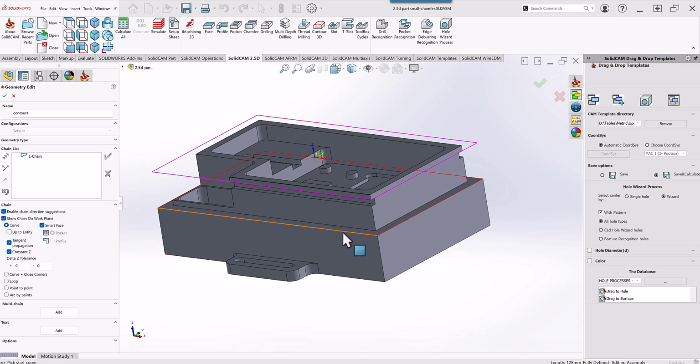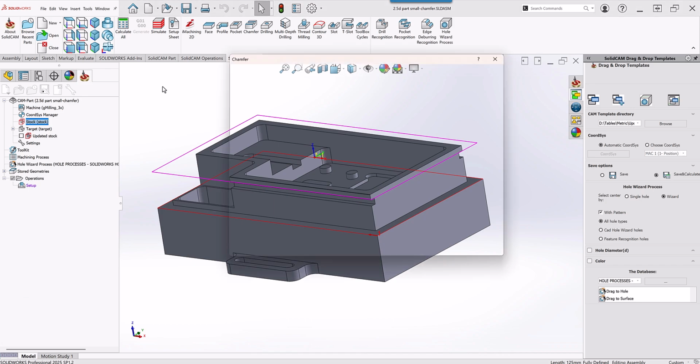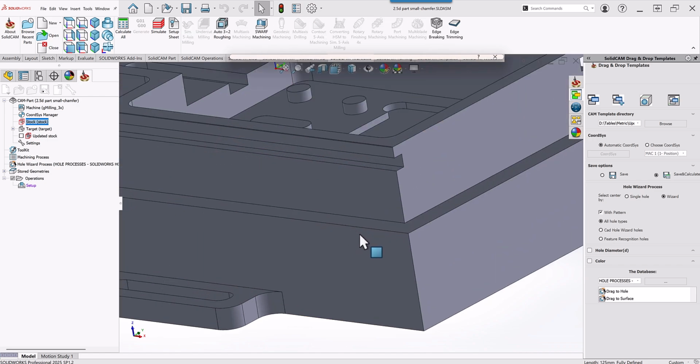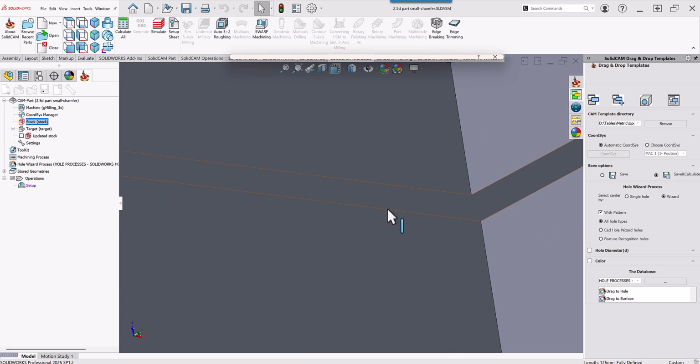It should be noted that even though we have target protection, let's go back into my field, even though we do have target protection available, in essence what we'll be doing over here is that we will be gouging this corner with the tool. In chamfer operation, we allow for the cutting edge of the chamfering tool to actually gouge the target itself, removing the sharp corner from this part.